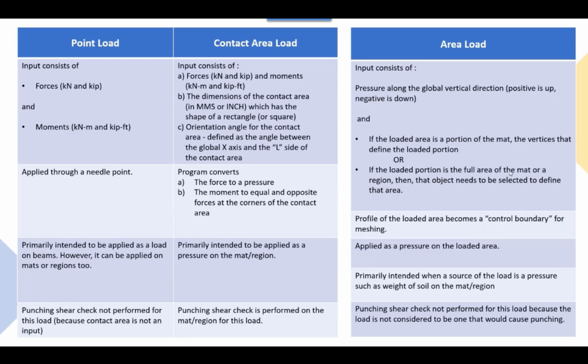Before we assign loads to the mat foundation, let's take a look at the different types of loads that can be assigned in STAAD Foundation Advanced and the variables that you will need to define to create them. First, let's take a look at the point load option. Point loads can be defined in the program as a point force or a point moment. In addition, if you plan on assigning your point load with a contact area, you will need to enter the dimensions of the contact area and the orientation angle.